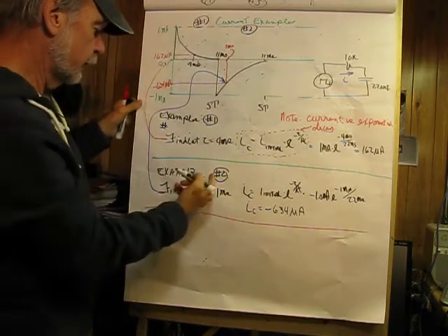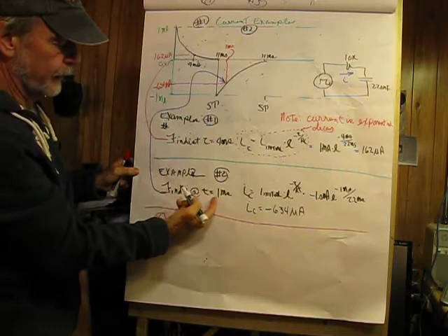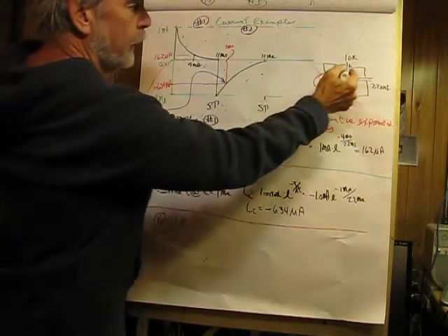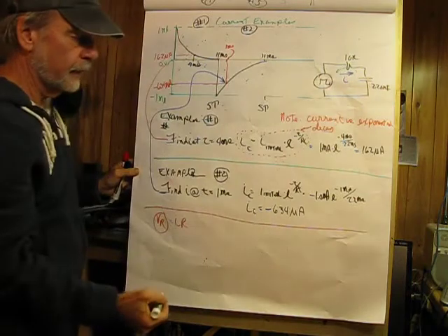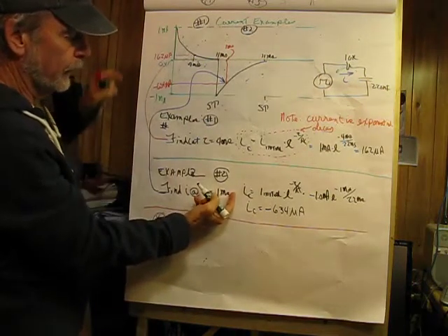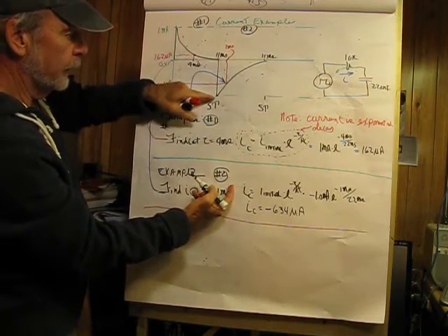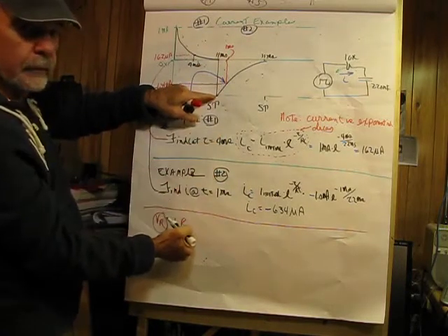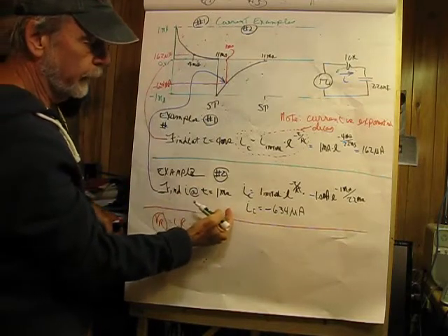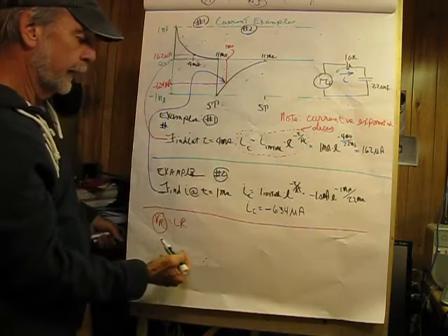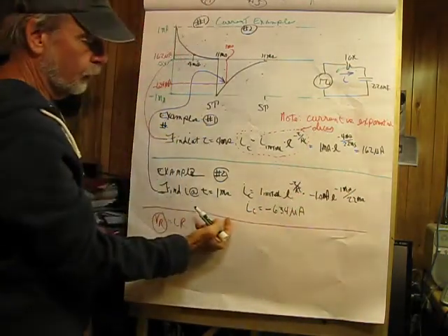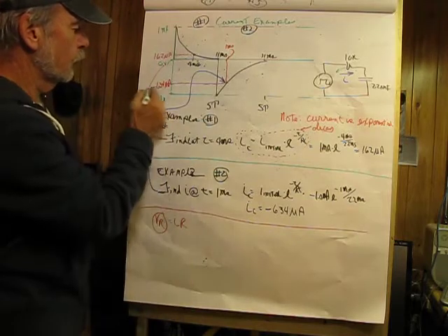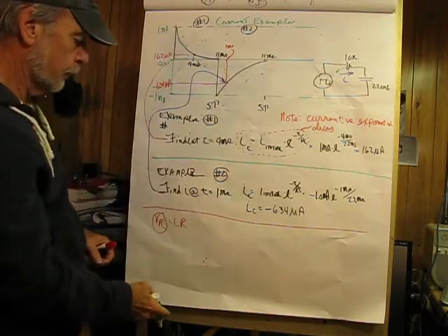And now if we take a look at number 2, and we want to find I at say t equals 1 millisecond, this is going to be, again, where the physical current is flowing opposite to the defined current. Everything is true as before. I initial is going to be negative 1 milliampere. And that's because the voltage of the source just switched negative. And in doing so, we end up with a negative 1 milliampere. And applying this equation to it, we see that the current flow in the capacitor, and for that matter the whole circuit, is going to be 634 microamperes at 1 millisecond.